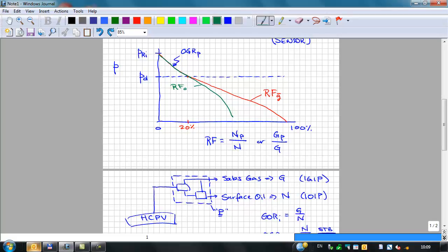So the capacity to vaporize the C7 is great at 1 bar and 280 degrees Fahrenheit. But you have to have something to vaporize it into. By the time you reach 1 bar, how many moles of gas do you have? You don't have any moles of gas. I mean, there's a gas phase there, but there's not very many moles. So it saturates with C7. Once it's saturated, what's left is most of the C7 in the oil.